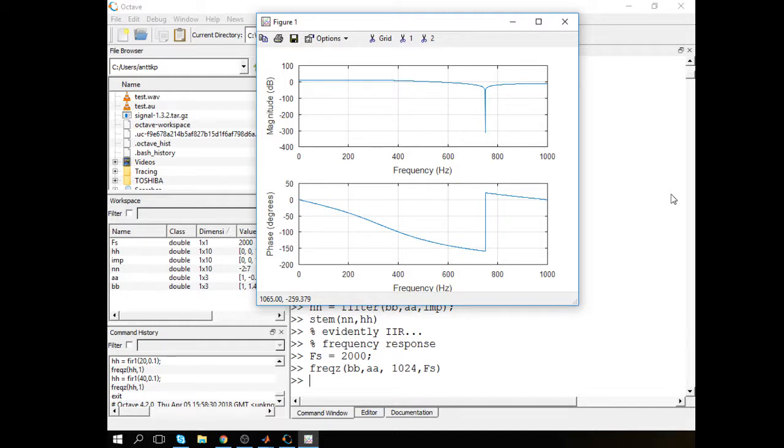You probably got something a little bit different, or did you? Oh yeah, of course. So actually, I ended up having that zero point on the unit circle. It means that it dips really, really deep on the magnitude response scale.